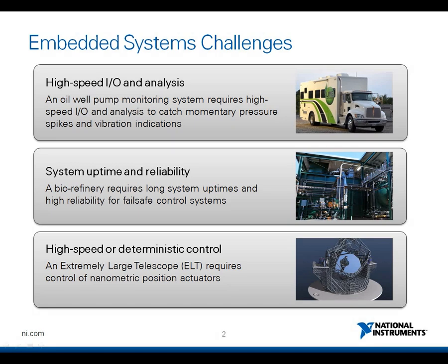Finally, the other aspect you mentioned, which is systems that require high speed and highly deterministic control, a good example would be an extremely large telescope such as ELT. These devices use nanometric positioning actuators and therefore require very precise control. Now you could attempt to solve these applications with a processor-only solution, but here you might encounter some shortfalls.